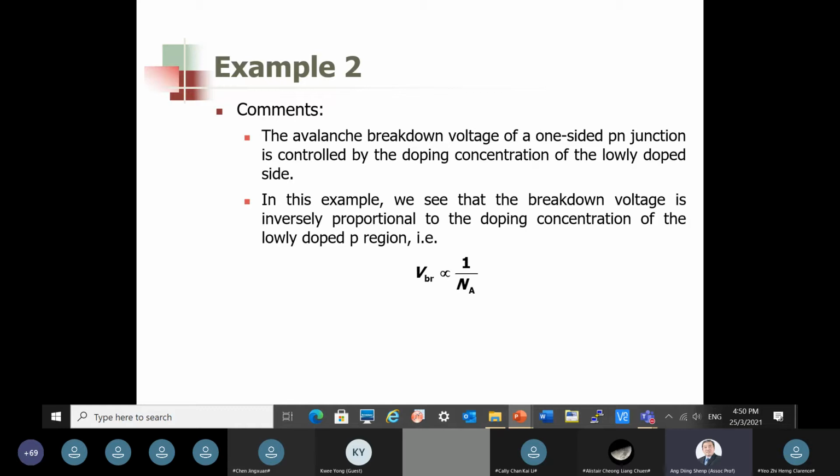Zener breakdown is non-destructive because the current flowing through the breakdown diode is controllable. There is no chain reaction that causes the current to increase uncontrollably, because in Zener breakdown, the current flowing is limited by the tunneling barrier.